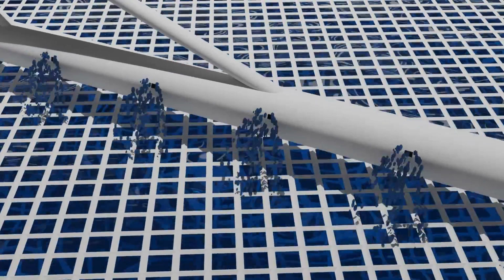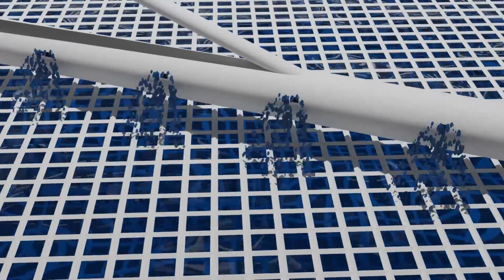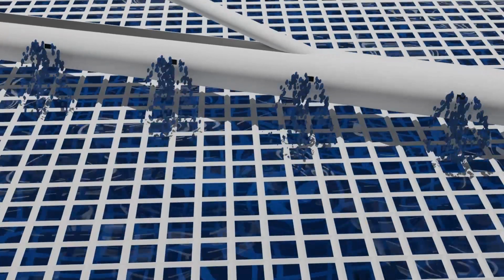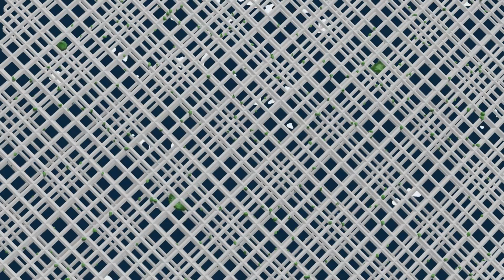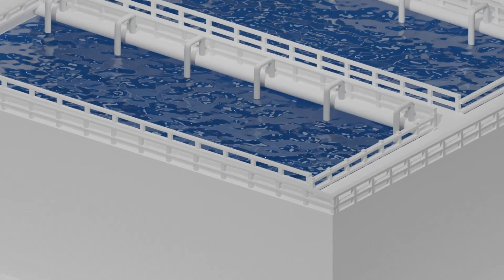In this filter, a large rotating arm releases the wastewater onto a layer of plastic media below. The plastic mesh separates all the algae and allows it to clump together. Next is the aeration tank, where organic matter breaks down further.